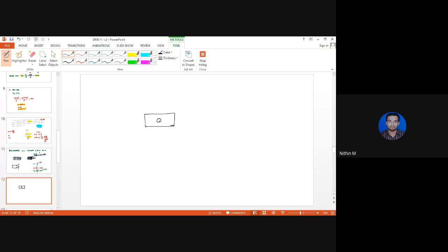Here you assume that this is the same plate that you had encountered there. Now what is this hole representing? This hole is basically required for applying lubricant to that screw. Now what will happen if there is no hole? If there is no hole, lubricant cannot be put into the lead screw, which will damage the screw itself. It will damage both the vise as well as the screw because of excessive relative motion. There will be excessive friction. In the absence of lubricant, it will lead to wear of the component.